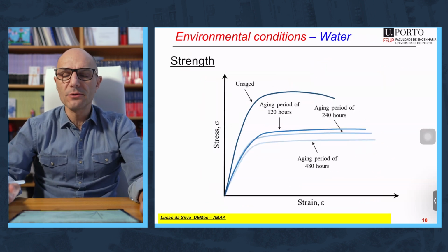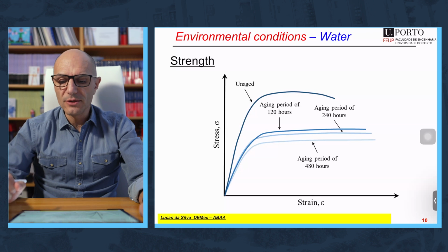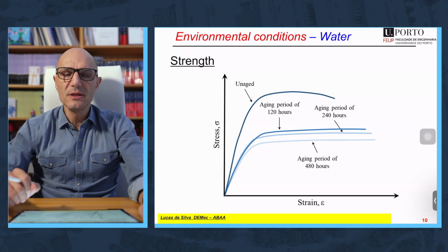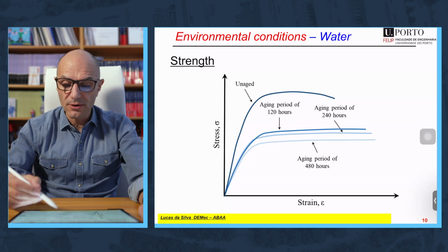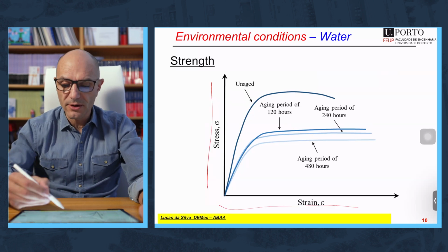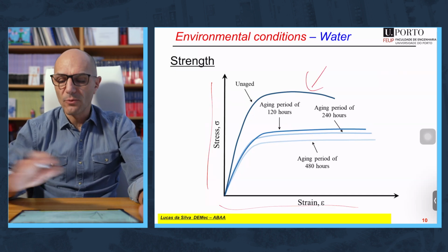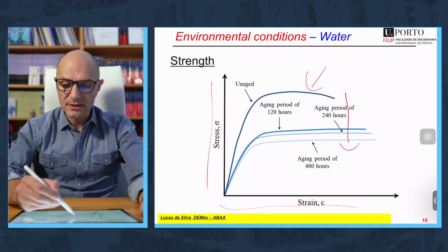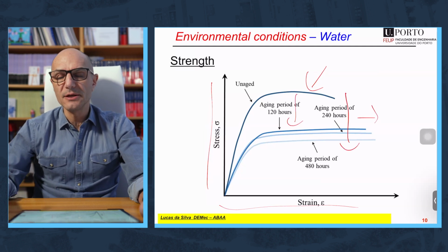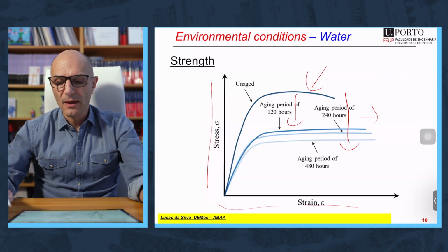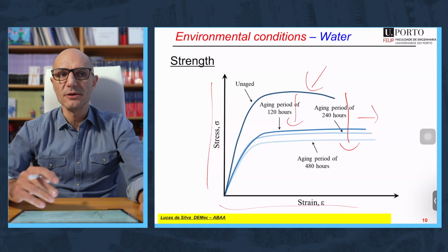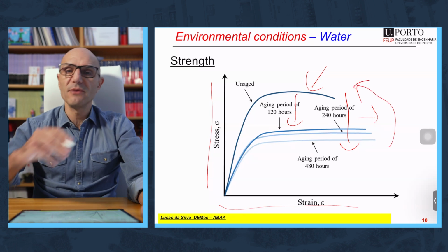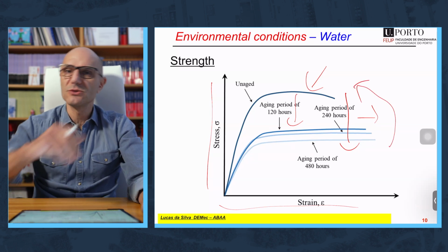Will the adhesive be in contact with water? Yes, then you also need to understand how the properties of the adhesive will change with the absorption of water, and it will change a lot. Again, stress-strain curve: this is without water, and after periods of immersion in water. You can see that the strength decreases and the ductility increases. It's not too bad actually. And if you don't exaggerate and you don't create chemical damage, you can go back to the beginning if you dry the adhesive. Physical damage is reversible.